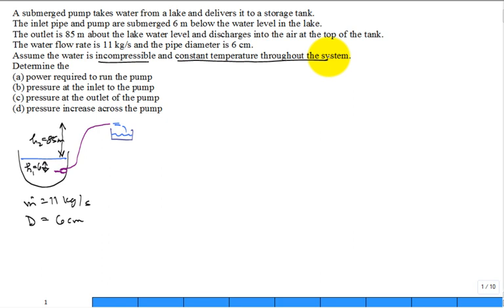An open system which is clearly defined, so anybody looking at your work can say, I know what open system they're applying that energy balance to. And so you're going to clearly define it by introducing a control volume. And that control volume is distinguished by a dashed line, which you pay a lot of attention to, where you cut, where it is.